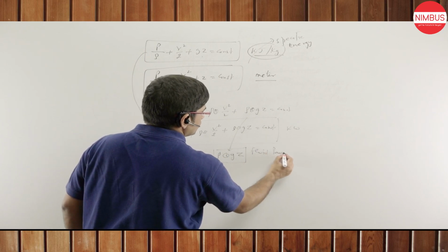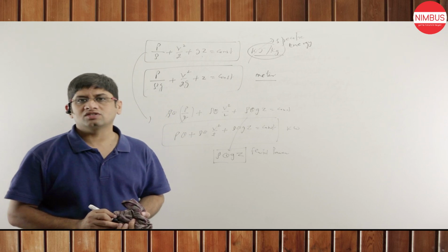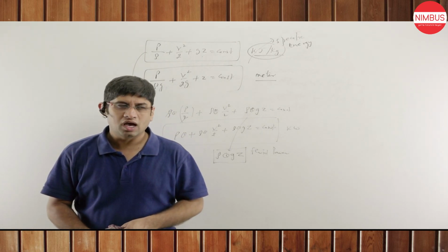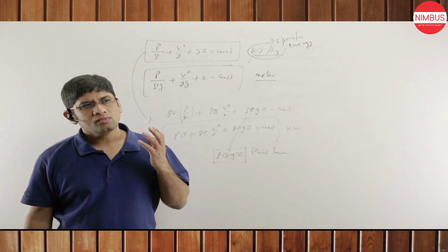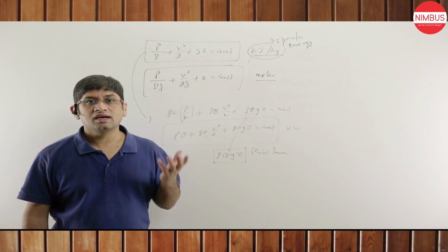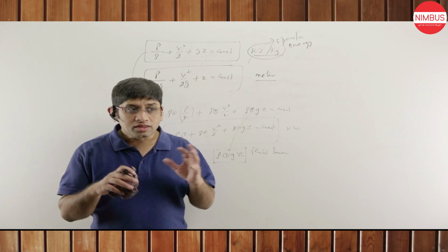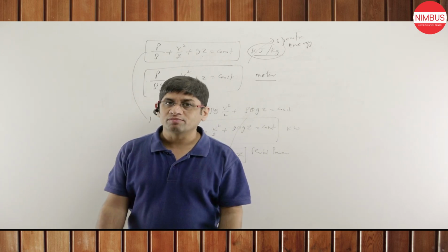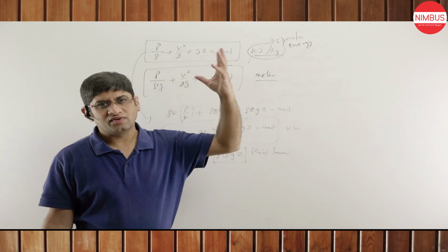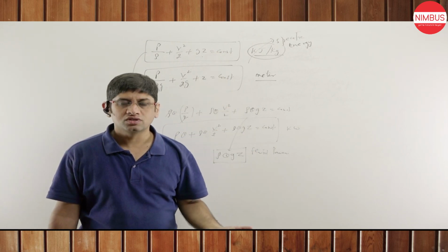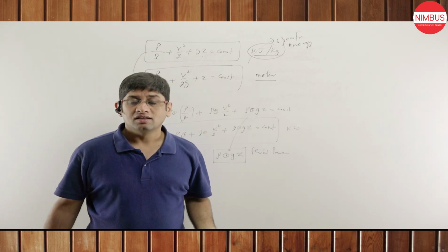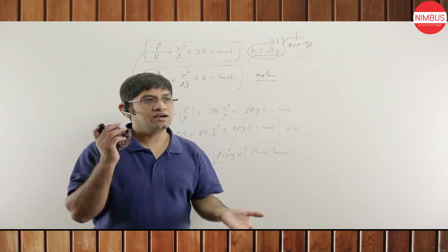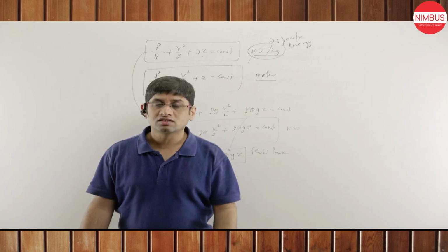Fluid power, you know, you people study something which is called fluid machinery also. Have you not heard Pelton turbine, Francis turbine, Kaplan turbine? Now all these turbines are installed on some particular fluid power basis. Now if suppose head is very high, then Pelton turbine is used. If discharge is very high, then Kaplan is used. If head and discharge are moderate, then Francis turbine is used.